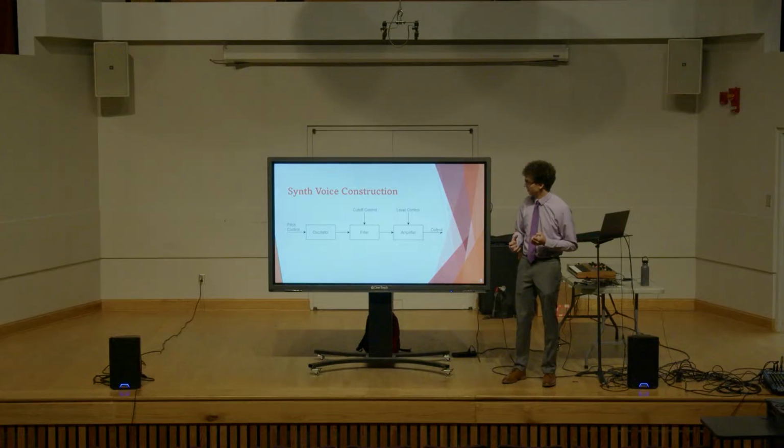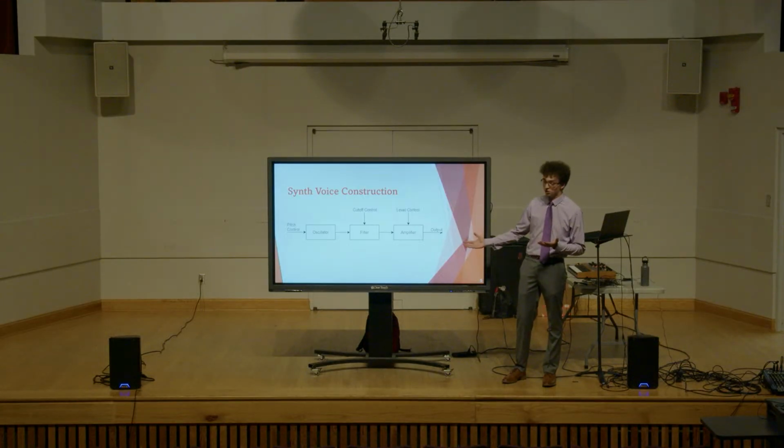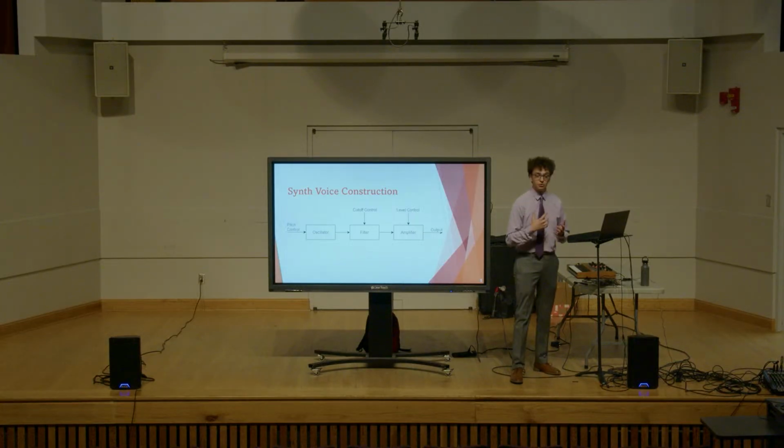The construction of a very basic subtractive synthesizer voice is your oscillator, which just creates a wave. It does nothing else but create one constant running wave. That wave is controlled by a pitch control and is run into a filter, which then cuts off harmonic information, either highs, lows, mids, whatever that filter specifically does.